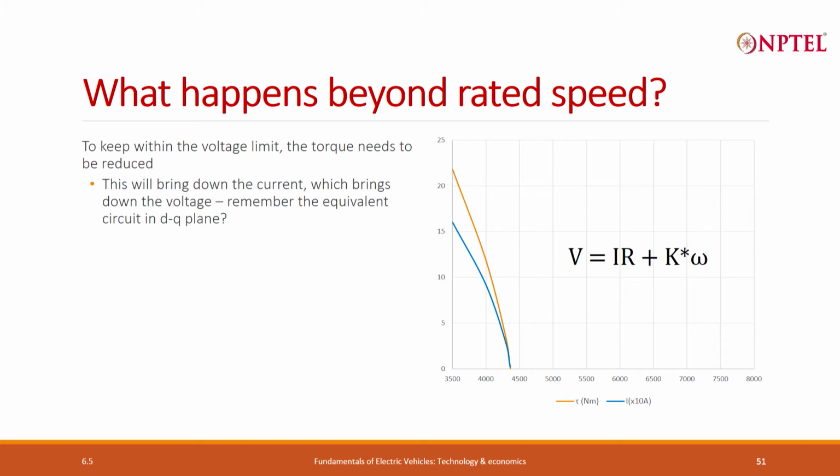The total voltage is the sum of the ohmic drop and the back EMF. I am ignoring the transient term, okay. I am going at a steady state. So, there are two terms. As good designers, we always design the motor with the lowest possible resistance. Let us say it is 1 in whatever units, 1 ohm, 1 milliohm, something 1, so that we keep the resistance low, which means the losses are low, the heat generation is low.